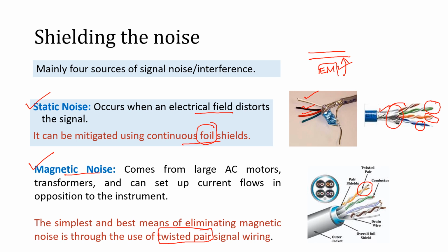Two wires taken together are twisted with each other, and that is how we cancel the flow of north and south through those two conductors, because the wires behave like conductors in a magnetic field. By twisting those two conductors, we cancel that magnetic field.